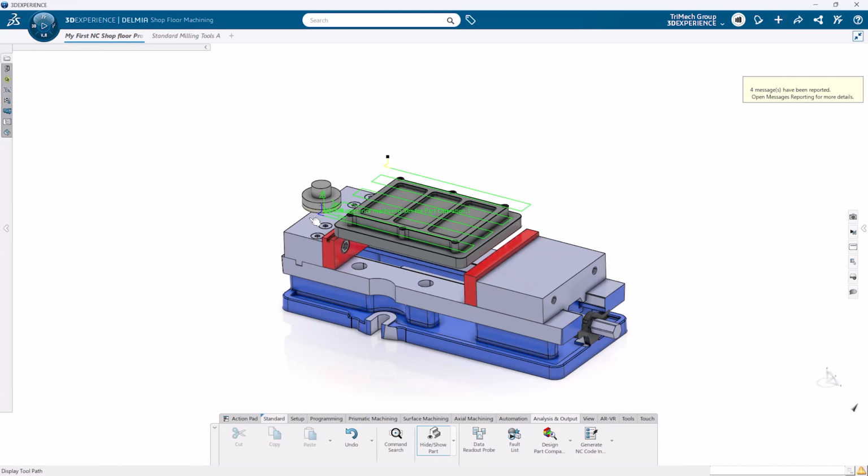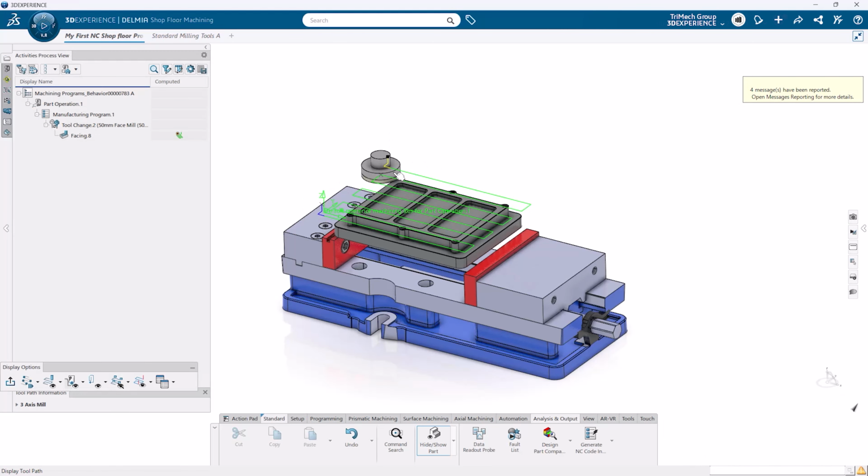On review, we don't actually want that second horizontal motion, so we'll head back to the Macros tab and set both drop-downs to build by user, and click the pencil icon to edit them. In this dialog box, we can click components of the path and simply delete them or modify dimensions by double-clicking on them. The macro will automatically adjust, and we can edit the second motion or copy and paste the path to the other macros. Once we're happy with the toolpath, press OK to save it.